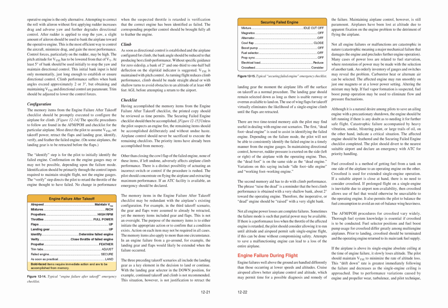The second memory aid has to do with climb performance. The phrase "raise the dead" is a reminder that the best climb performance is obtained with a very shallow bank, about 2 degrees toward the operating engine. Therefore, the inoperative, or dead, engine should be raised with a very slight bank.